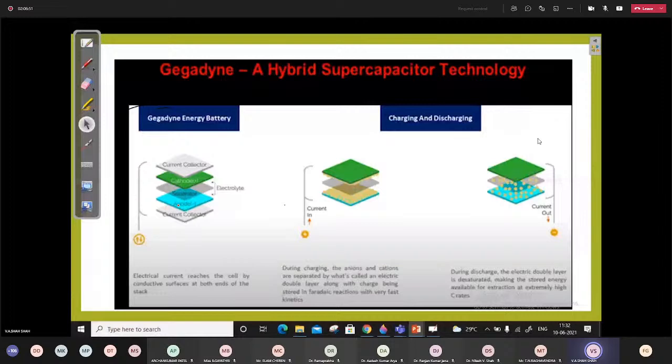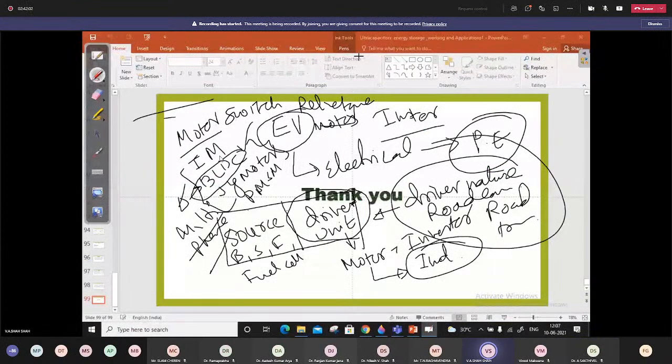Usually for two-wheelers and three-wheelers they prefer the BLDC motor, but BLDC and synchronous motors are largely a monopoly of China. Cost is also a factor in the use of this permanent magnet type of machine, and that's why even companies are focusing on the application of induction motors in their vehicles.